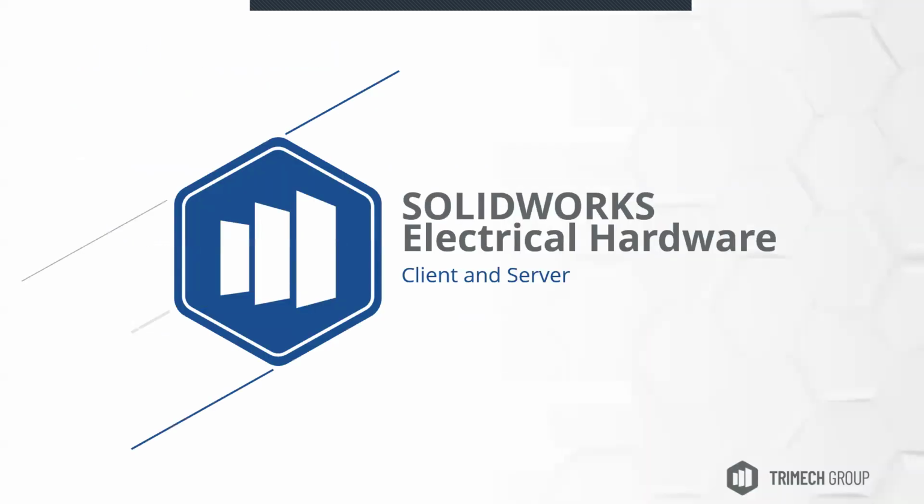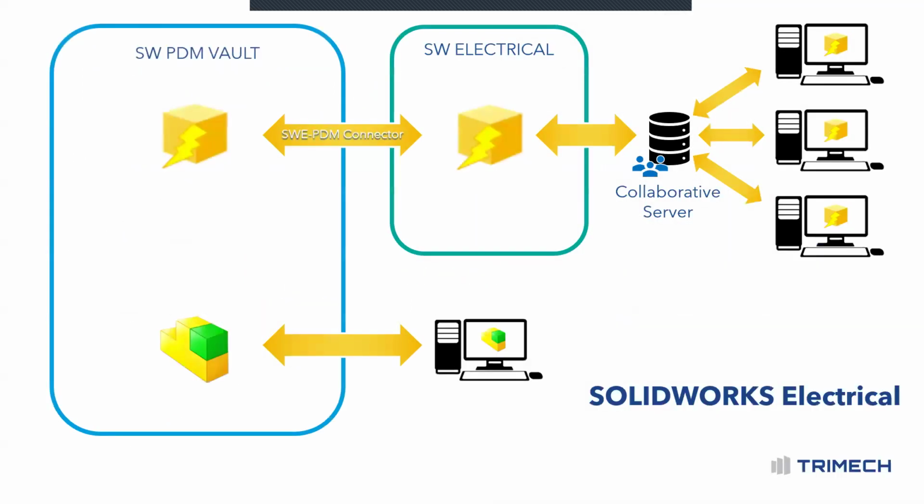So let's talk a little bit about the architecture here. SOLIDWORKS Electrical, again, is not quite as straightforward as installing SOLIDWORKS CAD. It's actually connected through a collaborative server. So there's a SQL database that is tracking what components are being put down on the paper and all of the associated information with those components.